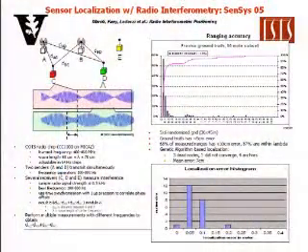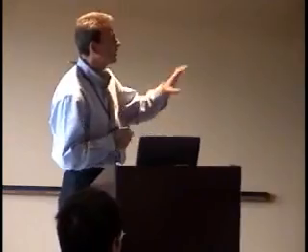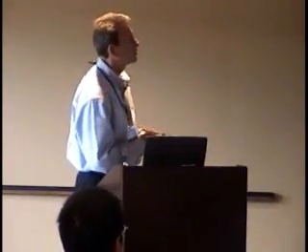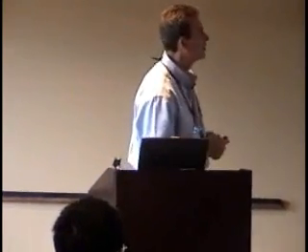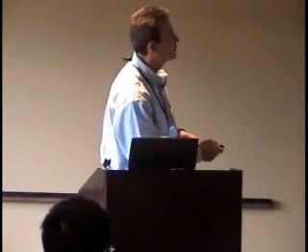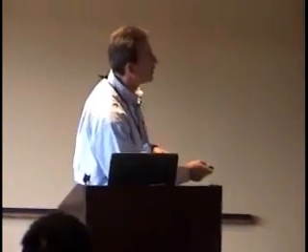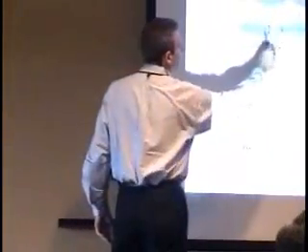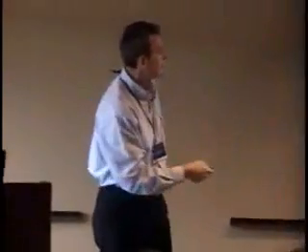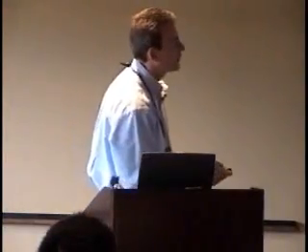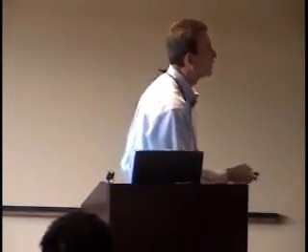So at ISIS, we're looking at different research problems, and I asked Akos Ledeczi to give me some of his slides about some of the recent developments. This slide describes a new sensor localization algorithm that's going to be presented at SenSys next month. The basic idea is that two nodes transmit with a small frequency separation, and some receivers are able to measure the phase difference of this low-frequency beat signal, although they use the wavelength of the carrier, which is much shorter. And by just using this idea, you can achieve very good localization.